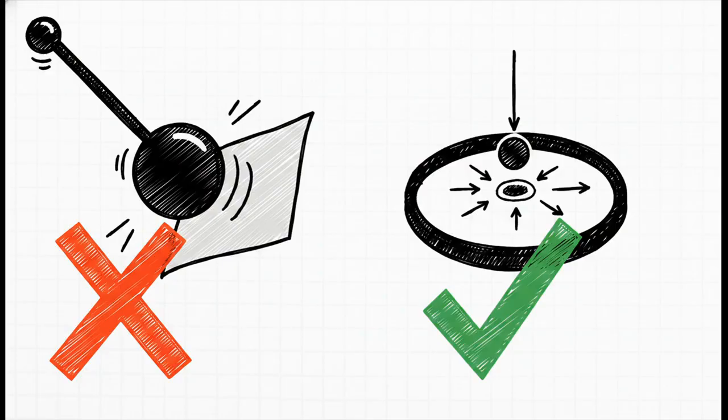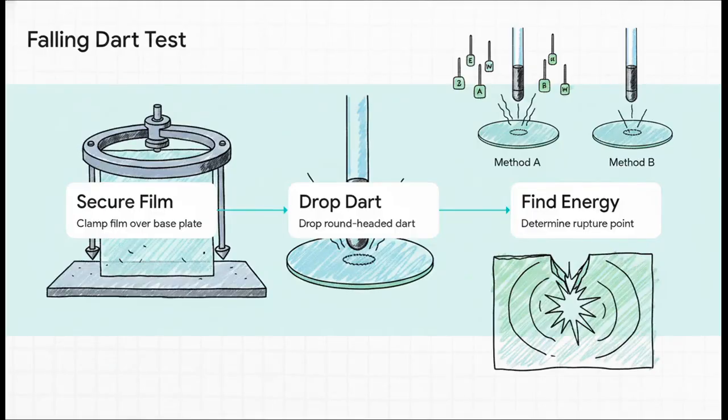They simply do not duplicate the multidirectional or polyaxial impact stresses that thin films, packaging sheets, or even finished blow-molded bottles experience out in the real world. To measure the true practical material toughness of these products, we use drop weight tests, and specifically the free-falling dart method. For testing plastic films, we use standard ASTM D1709. The procedure here is straightforward, but it is highly effective.